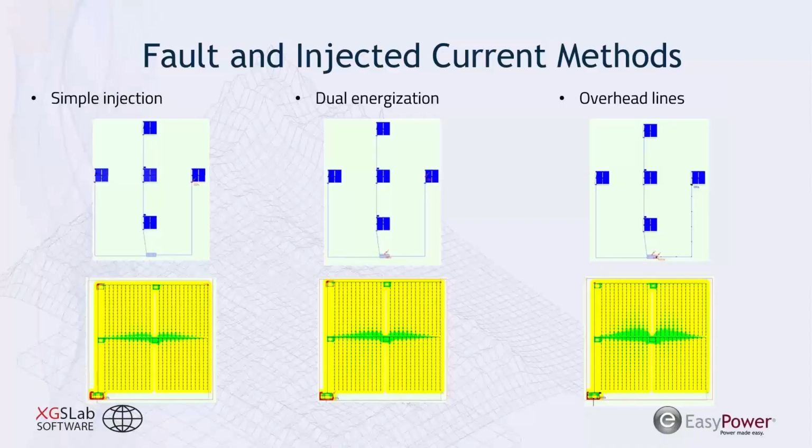So typical practices are that you might take multiple measurements at each one of your areas of focus. So for a site like this that's dispersed, we'll have shorter soil resistivity measurements, maybe 100-foot A spacing at each one of these points. And then we might take a 1,000-foot traverse, 1 or 2 of those, in order to characterize deeper soil layers, whatever we can physically perform based off of the site's geometry and what site permissions allow, as well as your test equipment's capabilities. So you typically need a more powerful or a more sensitive soil resistivity meter in order to really accurately measure these.